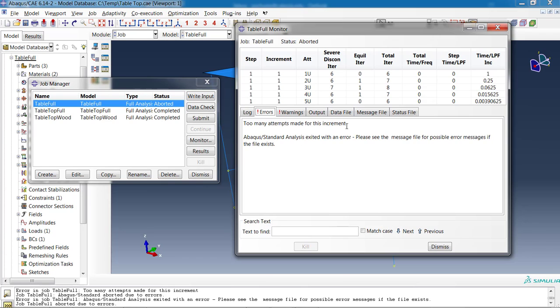As I mentioned at the end of that tutorial, that error typically means that Abaqus cannot identify a unique solution to the problem. In other words, it can't identify where all the nodes ended up. That's usually an indication that you've created a dynamic problem rather than a static problem. So you are under constrained.